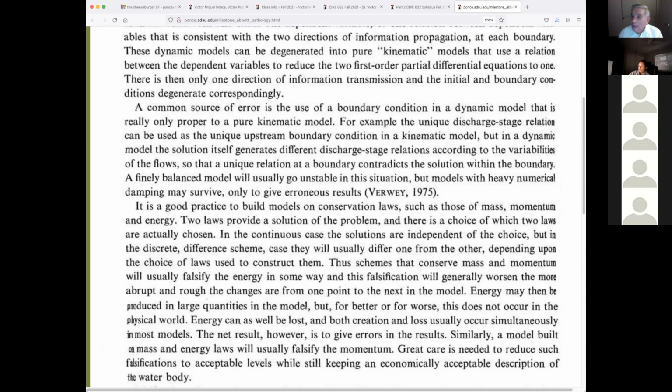What is this? Well, in the dynamic wave models, there is a weighting factor which is called the theta weighting factor. And you as a user can control its magnitude. If its magnitude is 0.5, there's no artificial or numerical damping, no filtering of the noise. But if you increase it to 0.6, then you'll get some damping. 0.55 is the recommended value. The lowest recommended value is 0.55. But 0.6 is a little better. You can go to 0.8, a little better from the damping standpoint.